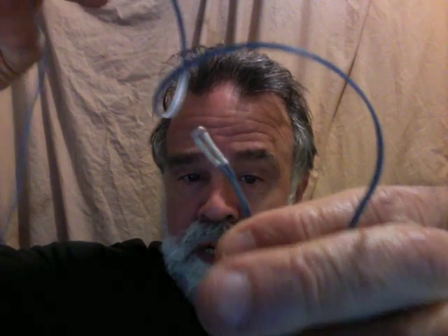Here's one of the electric eyes, which was used on the S-gauge. Fred Cupp got this for me. This short part comes from a mail-order electronics firm, I believe, like Mouser or DigiKey or one of those. And Fred soldered these extra wires on it, so it's about 3 feet of wire as it is now. There's no electronics associated with this. You just basically have 2 ends: you hook one end into the ground of the mini panel, and you hook the other end into the input wherever you're going. For the S-gauge, I think I used input 11.